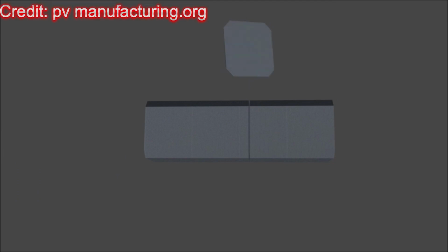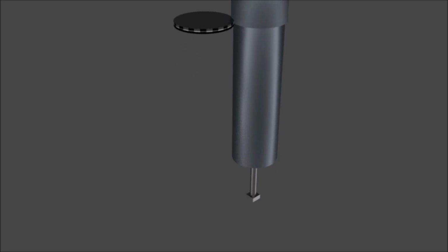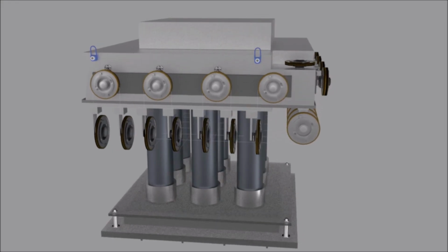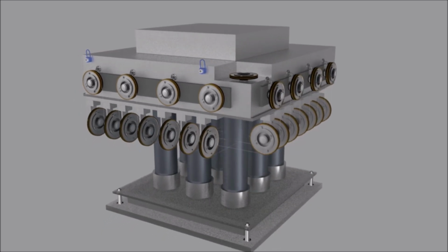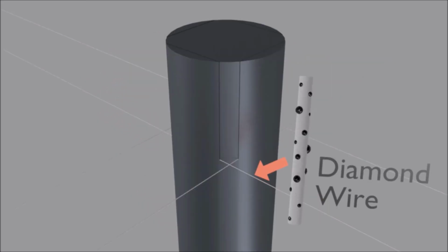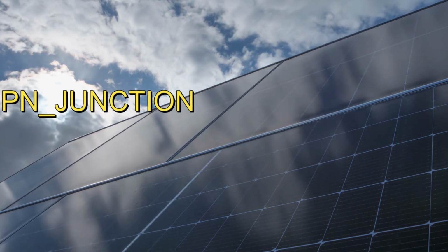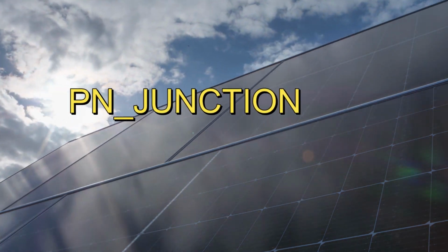Here's an important fact. Because the original ingot is cylindrical, the first wafers are naturally circular. However, circular cells waste valuable space inside solar modules. In order to improve the packing density and maximize active surface area, manufacturers trim the wafer's edges into square or pseudo-square geometries. Now begins one of the most important stages of the entire manufacturing process, the creation of the p-n junction. It's the region that allows sunlight to become electrical current.